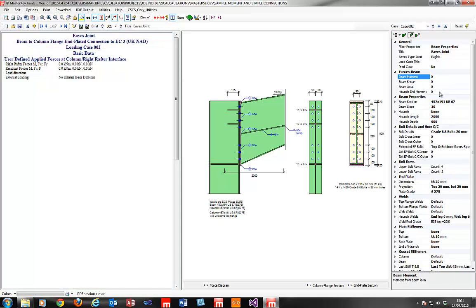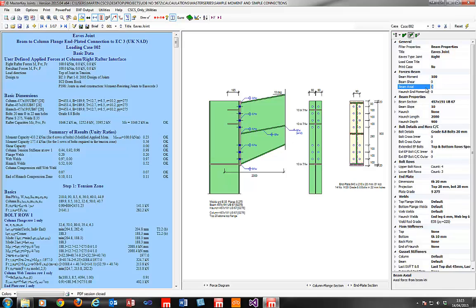If you want to add another case, let's pop that in, specify slightly different parameters there, and you now simply have the two cases. The case can have a title as well, which is something you couldn't have previously. So I have a dead plus wind case there, and that'll come in nicely in the output also.